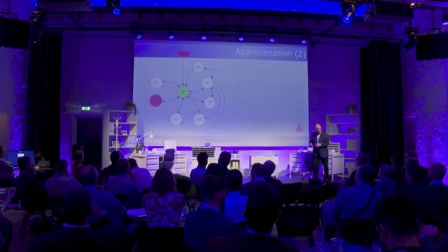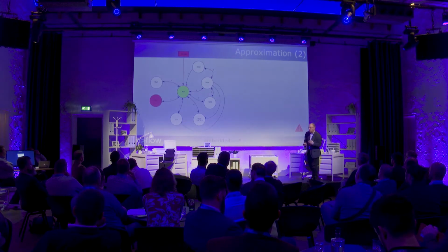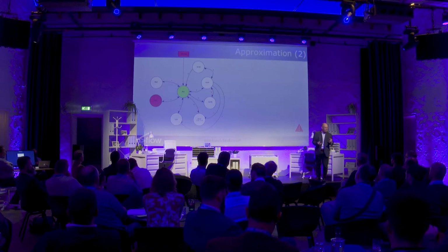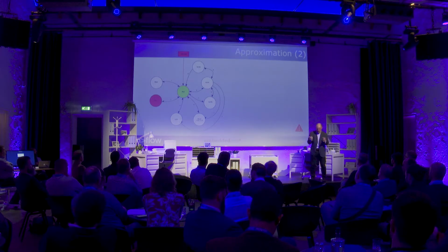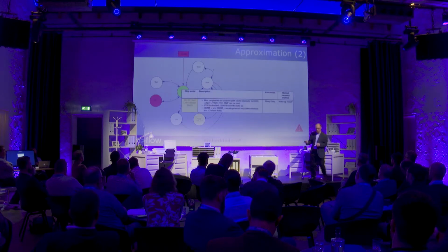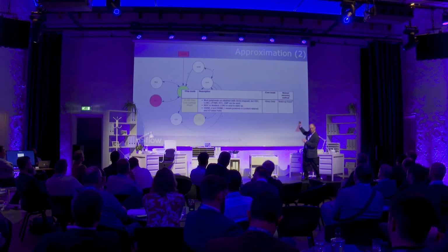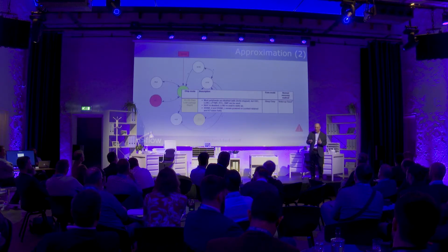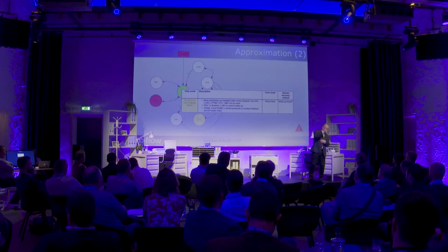Okay, and then here's the real problem, is that these microcontrollers are so complicated nowadays with so many different kinds of low power modes. Me as an engineer sitting at the desk thinking, right, we're going to spend 15 minutes in a low power mode. Well, yeah, which low power mode? So we go to the reference manual, and the reference manual says, very low leakage stop mode 3, and stuff about what the microcontroller can do in that mode. And you know, I have to do the design of the system and understand all these low power modes before I can do my graph of what mode I'm going to be in.